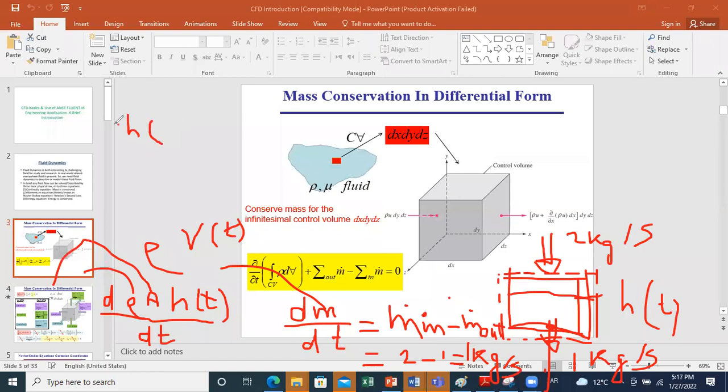the derivative of h with respect to time is a constant. And this constant is equal to 1 over the density of water times the cross-sectional area of my reservoir. So you'll obtain a constant. This means that h will vary in a linear way. So h will increase linearly with time. Here you didn't need to do a micro analysis.